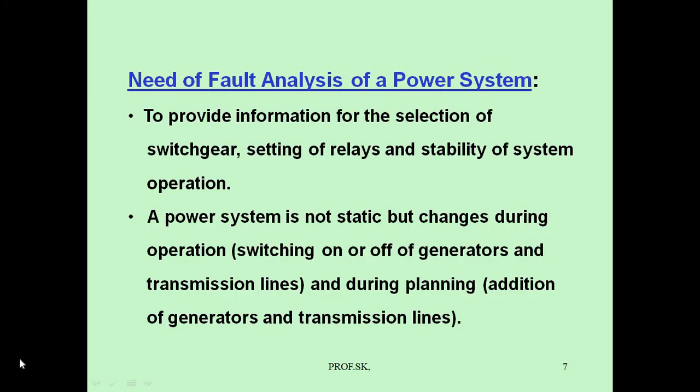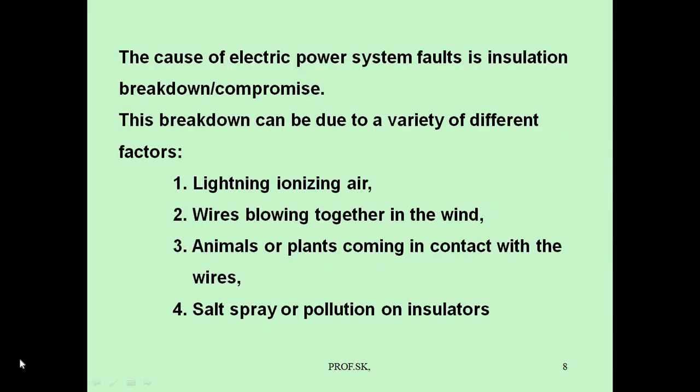Need for fault analysis of a power system. To provide information for the selection of switchgear, settings of relays and stability of system operation. A power system is not static but changes during operation, switching generators and transmission lines on or off, and during planning, with the addition of generators and transmission lines.